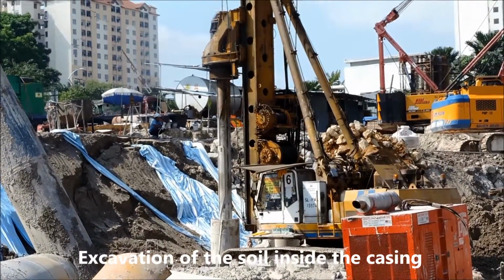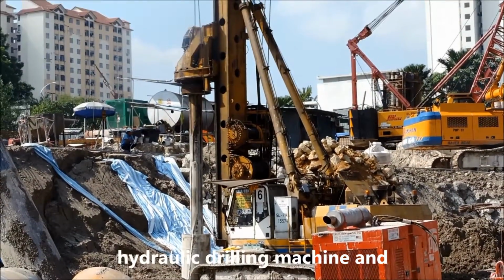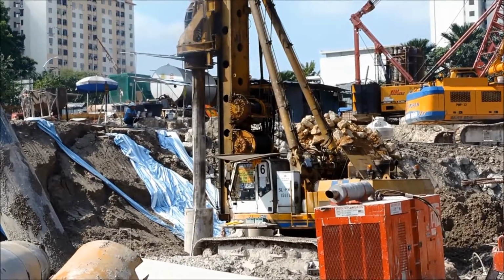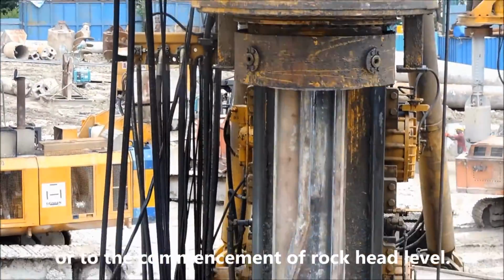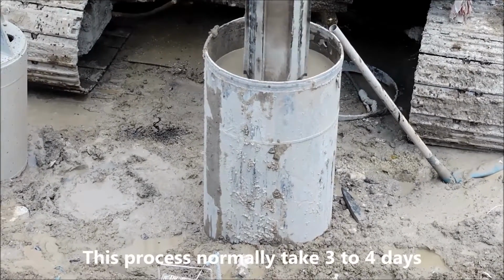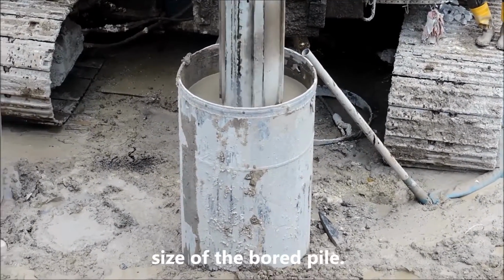Excavation of the soil inside the casing will be carried out using the hydraulic drilling machine and drilling bucket by rotary piling method. The drilling process will be continued to the design founding depth or to the commencement of rock head level. This process normally takes 3 to 4 days to complete, depending on the size of the bore pile.